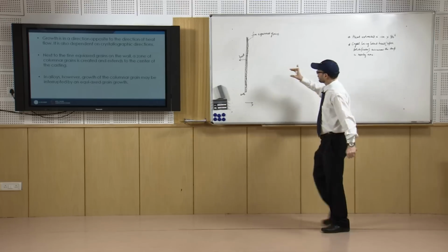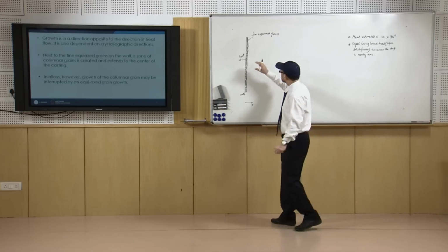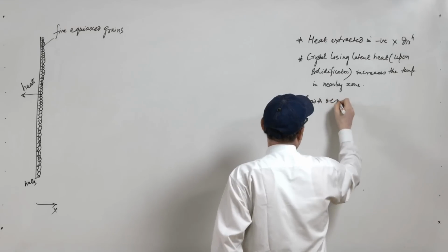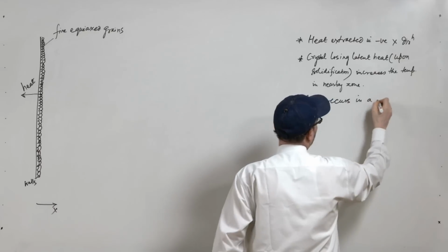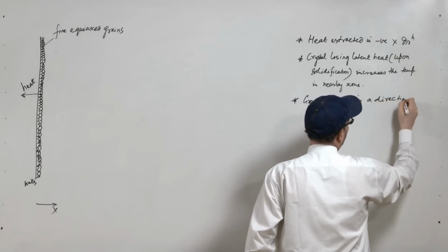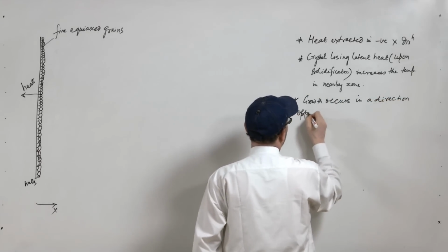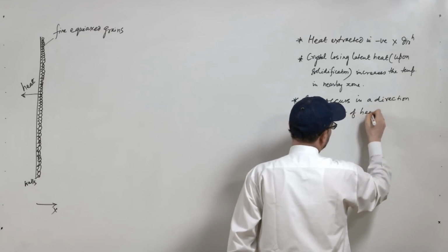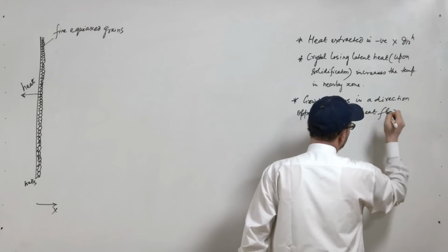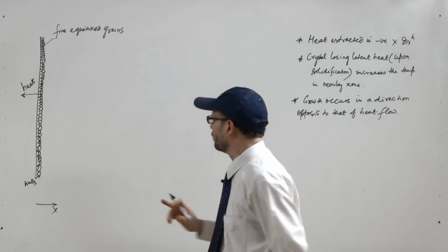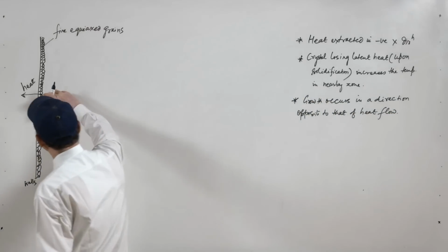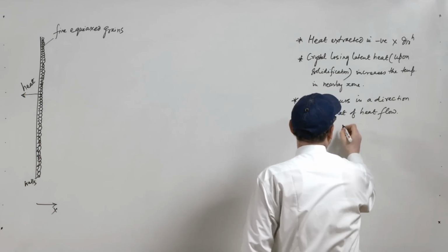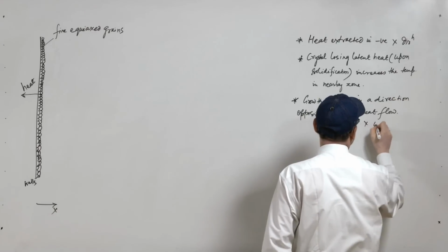Next, growth occurs in a direction opposite to that of heat flow. Since your heat flow direction is in the negative x direction, growth will go in the positive x direction.